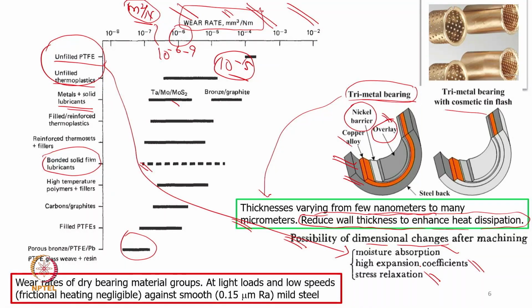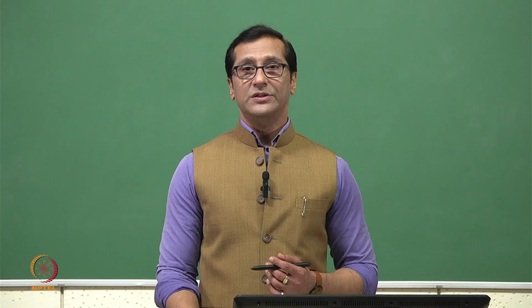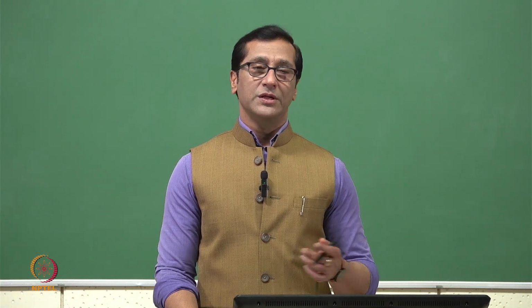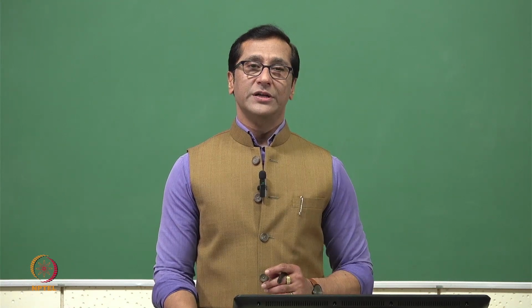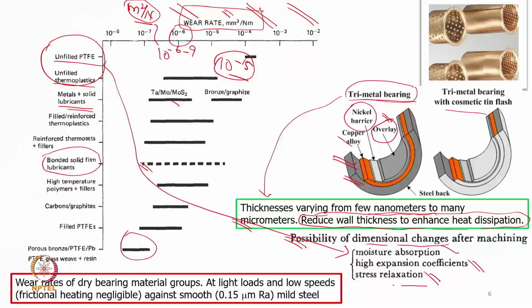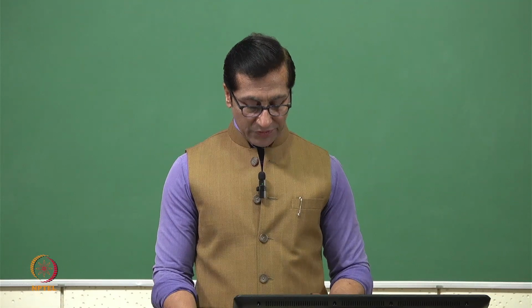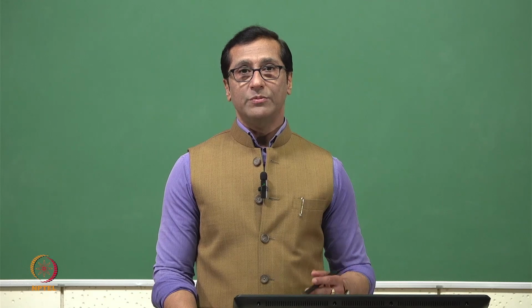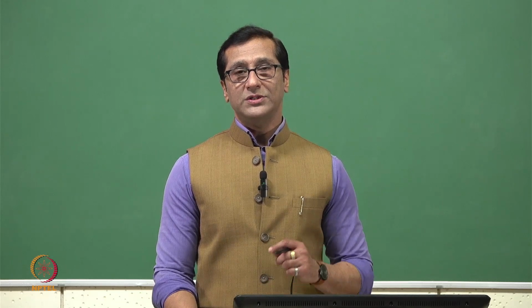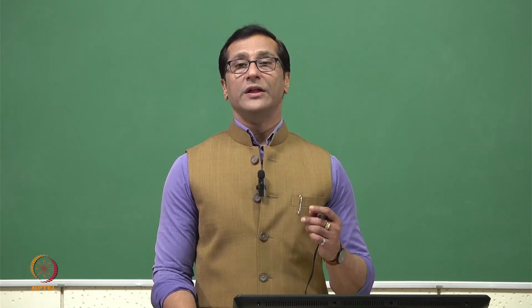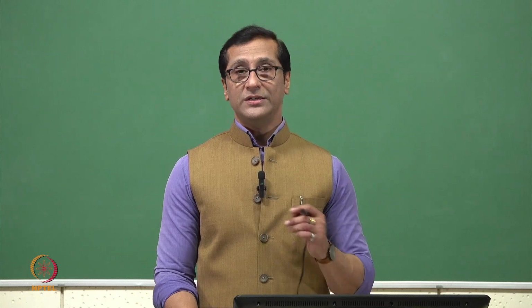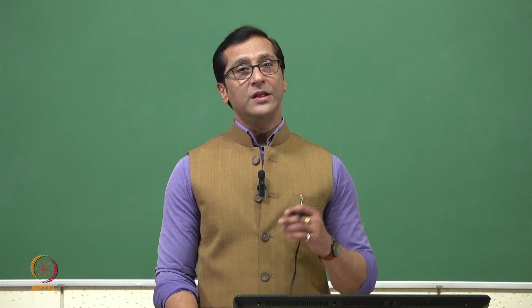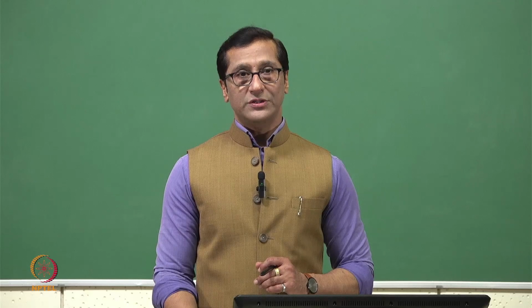Sometimes stress relaxation also occurs. Whatever surface treatment we do, and then allow it to operate in tribo situations, under stress relaxation the dimensional changes will occur. So we need to give more emphasis: we are choosing the right material and trying to do everything right, but if we are not accounting for how much dimensional change will occur, and how much reduction in clearance or increase in interference will occur, then it will not give satisfactory results.